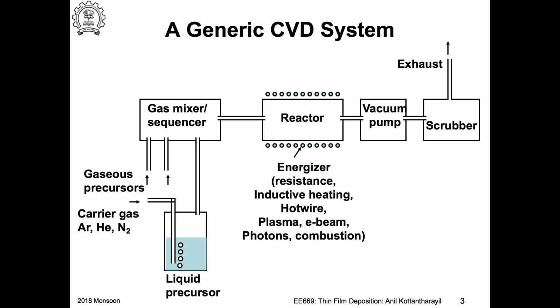But on the other hand, if I actually use a plasma, then what would happen? You will also create a nitrogen plasma. You will dissociate nitrogen molecules into nitrogen atoms, free radicals, excited states. That can react with your chlorosilane, and that leads to a nitride deposition. So, you will not get pure silicon oxide. Okay, so it is very important, the carrier gas.